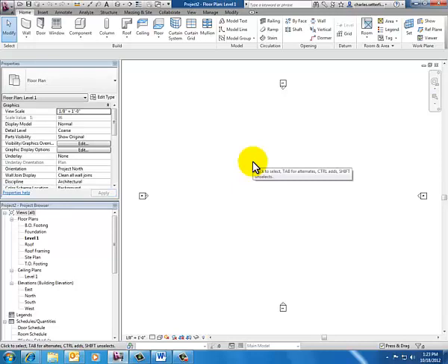So this office building that I'm going to do, I want to make this thing 120 feet long and 60 feet deep. So to help myself get organized, I'm going to use a grid system to do that with. So the grid tool is on the Home tab. The Home tab is where we are by default when we open this thing.